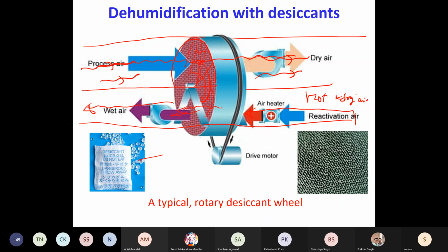It is normally difficult to dry. Anyway, we were drying our air using the silica gel. So where will we get this hot and dry air? What we do is we just provide hot air. When you raise the temperature of air, if you remember, Pv over P sat at the temperature of the air, so if you raise the temperature of the air itself, then you have scope of having higher moisture content in this incoming air.